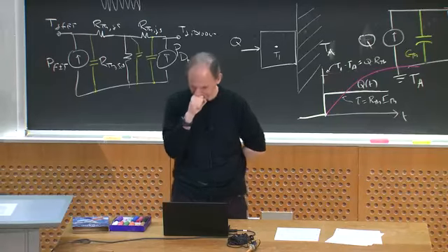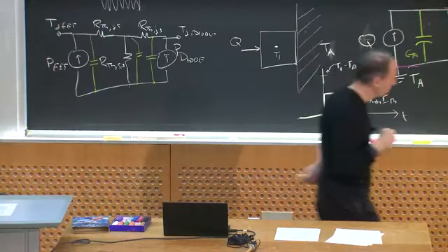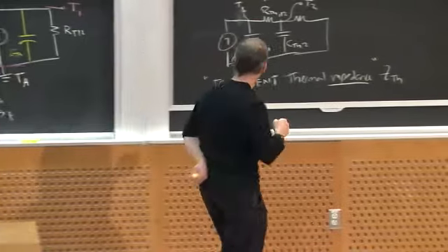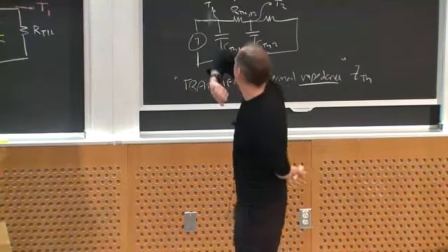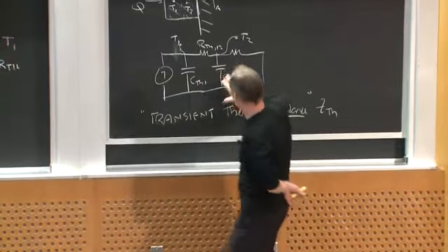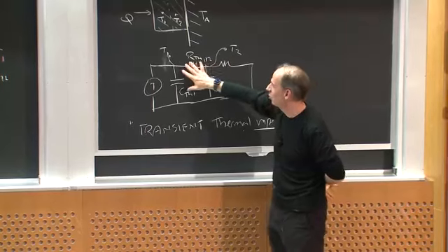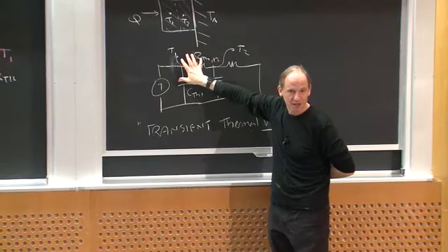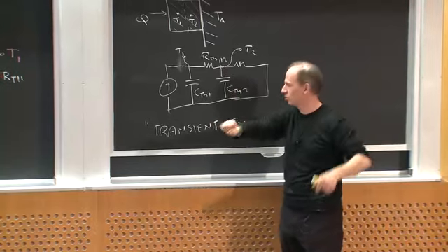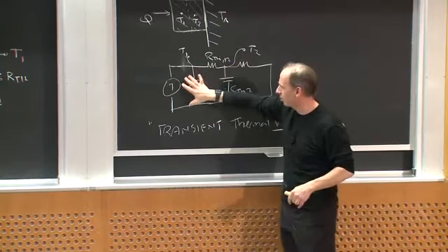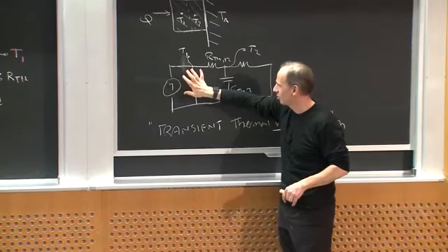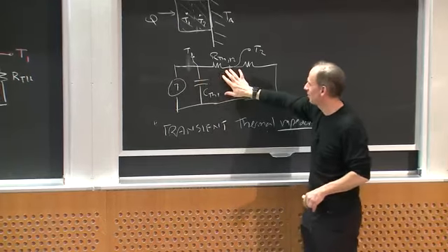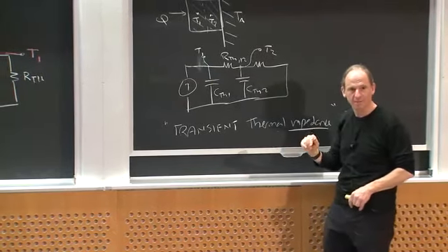Okay? The other thing I should tell you is that you could somehow extract that model and come up with a thermal model for the device. Maybe it's only 1 RC that you approximate it with. Okay? But in a complicated big module, it might be a more complicated model because there might be like the thermal capacitance of the silicon, the thermal capacitance of the header, and so forth, right?